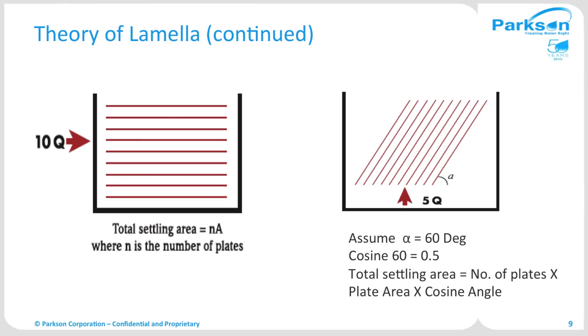If you reduce the height of the basin by a few inches and place such basins one on top of each other, that's called primitive shallow sedimentation. So in this example, you're actually looking at 10 compartments placed one on top of each other. So you can input 10 times the flow through the same basin without the compartments, I should say. And also the detention time is only 1/10 of the basin without the compartments.